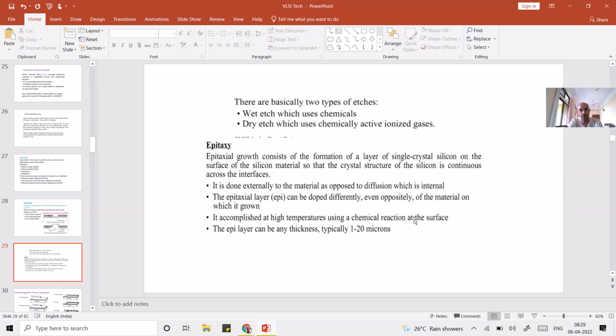One of those problems is latch-up in CMOS devices. But if you provide the epitaxy layer, this latch-up problem can be resolved. If the epitaxy layer is already provided in the material, then the device will not have the latch-up problem.